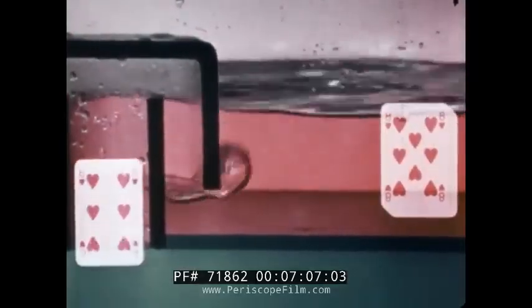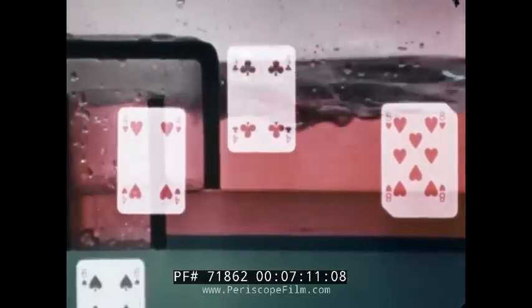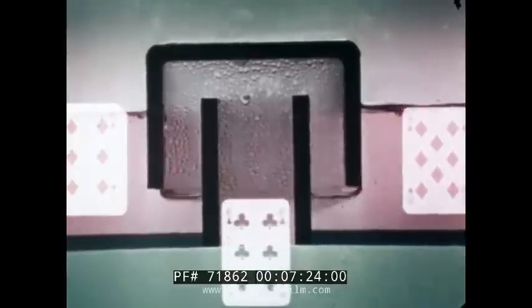In practice, however, the vapors are so closely intermingled, they never separate completely the first time. Some vapor which belongs on this tray is carried through with the lighter vapors to the tray above. Here it condenses, but now it's on the wrong tray.